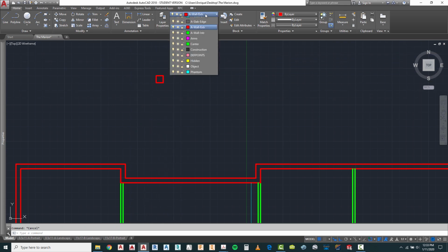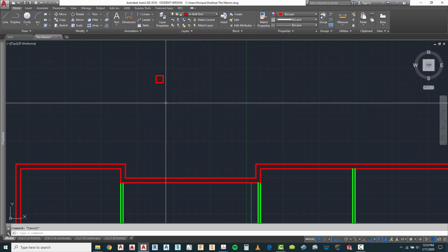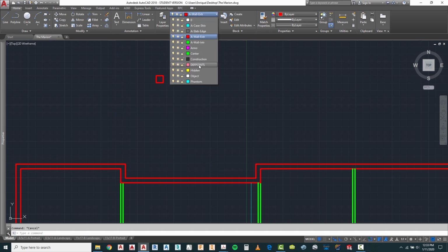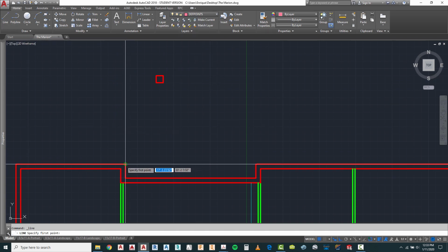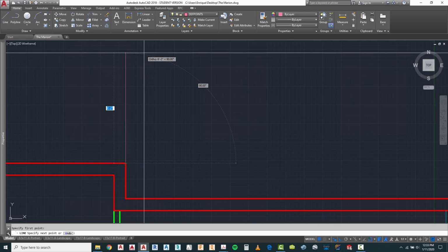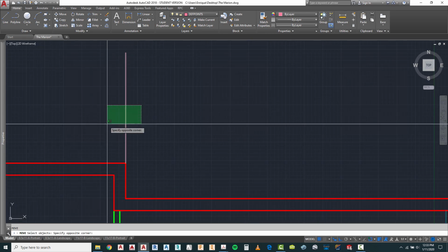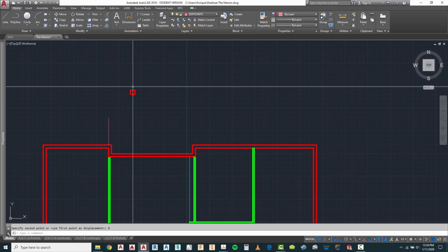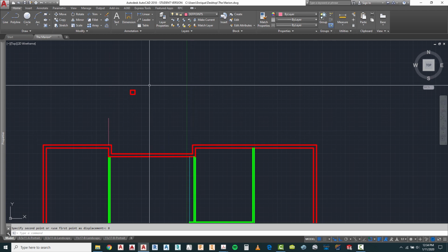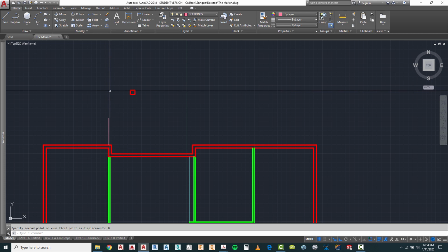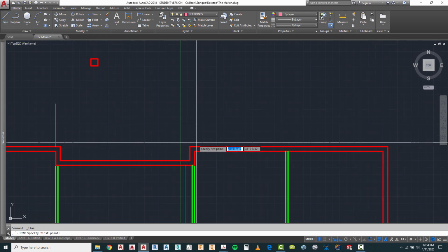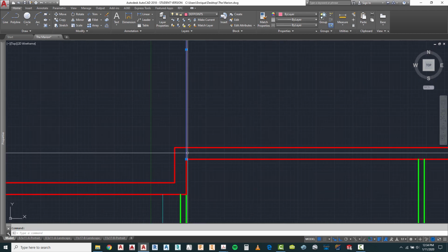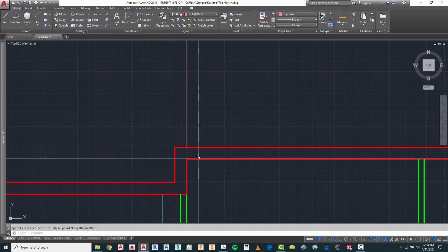Now I am going to align these with a certain line in here. I'm going to use a no plot line in here, which is depth points, and I am going to set it up right here and then move that line to the outside here 8 inches. That is where our upper indicator line for the beams that are supported here by the wall and the columns in here are going to indicate where the edge of our roof is. I could have also done it this way and then either trim this line or grab it by the grip going perpendicular to here.